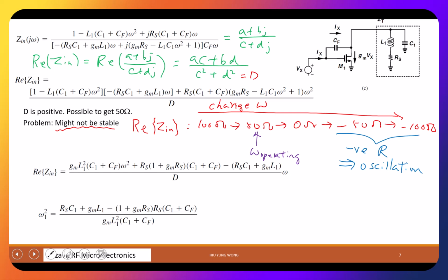Why will it screw up? Because when the power is large, when it's amplified, you bring your transistor out of the linear mode. You draw lots of current or whatever. You cannot say I add a filter so that I don't look at the 2 gigahertz, right? When your signal becomes very large, the transistor is no longer linear. You bring it to saturation and then out of linear mode. Make sense?